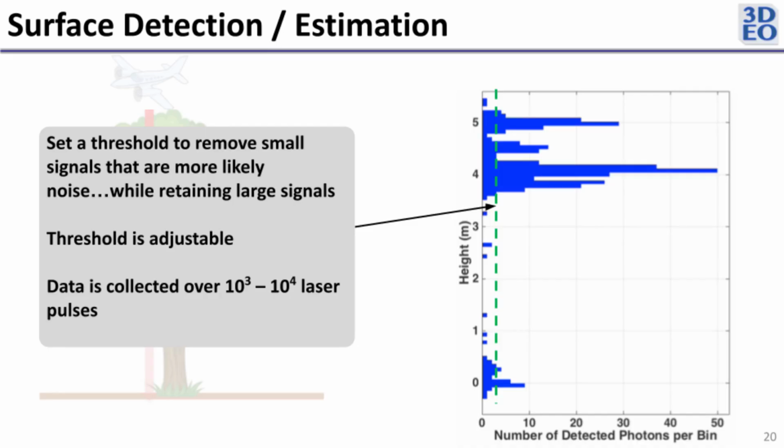In more traditional LiDAR systems, like your Regals and that sort of thing, they have a light pulse that comes in and it triggers a photodetector, and in their very sophisticated electronics, there's effectively a thresholding built right in. And on one laser pulse, you have to get up above the noise in order to say that's a real point.